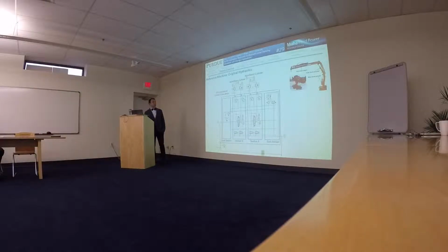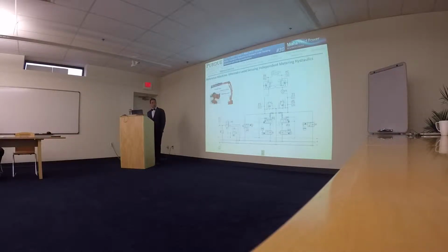And here in this picture you can also see the location of the pressure sensors, flow meters, and thermocouples that are present on the machine. This is a partial schematic of the hydraulic circuit of the new block valve, which is in particular a load sensing independent metering block valve. So now the peculiarity of this motion control system is that now we can control independently the 2 edges of the actuator, so the meter in and the meter out.